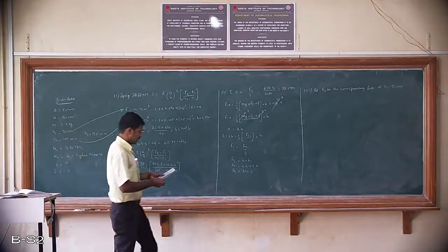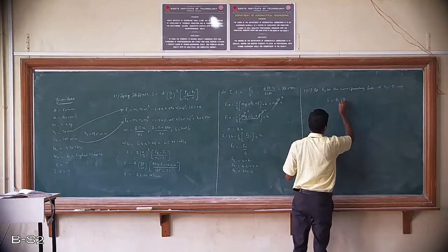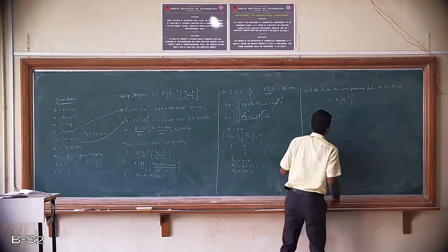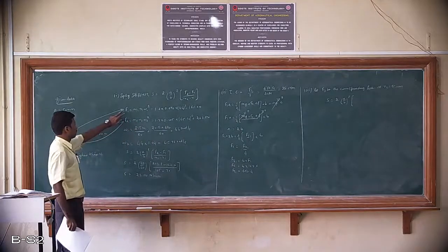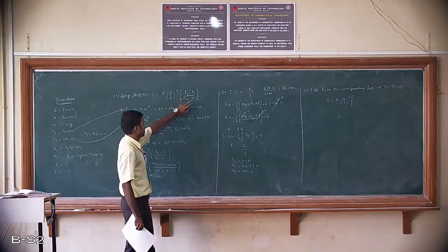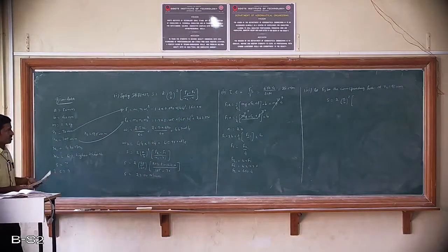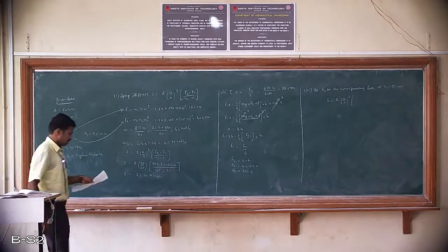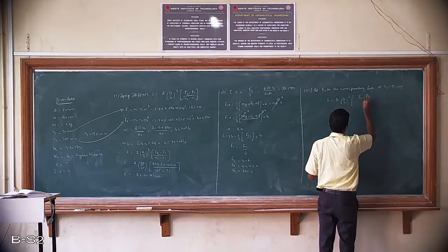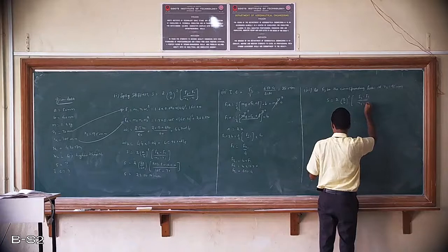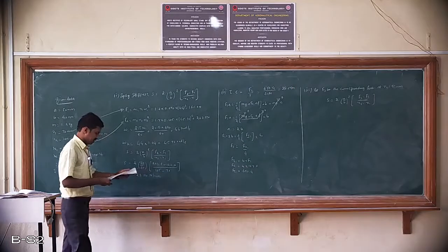So now the equation for S is given by S is equal to 2 into (A by B) whole square into the bracket F2 minus F1 divided by R2 minus R1. For radii R1, R2, the forces were F1, F2. Now the radius is R3, so its corresponding force is also F3. So the equation can be written as F3 minus F1 divided by R3 minus R1. So this is our equation now to find out the value of S.